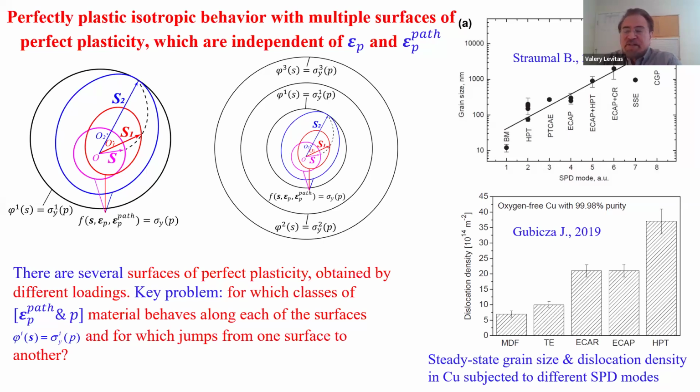Let's put it this way. Locally, everything is according to thermodynamics, but under the stress tensor. I showed you, we applied 1 GPa, but locally in the transformed phase, we have 7 GPa. Why? Because there is a strong stress concentrator due to dislocation pileups. So we follow dislocation rules, and we follow thermodynamics rules, but on the stress tensor and strain tensor, and in the presence of defects and strong stress concentrators due to defects.